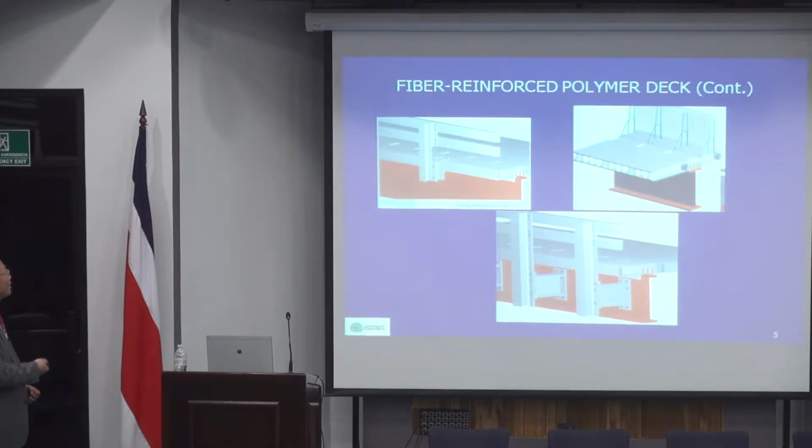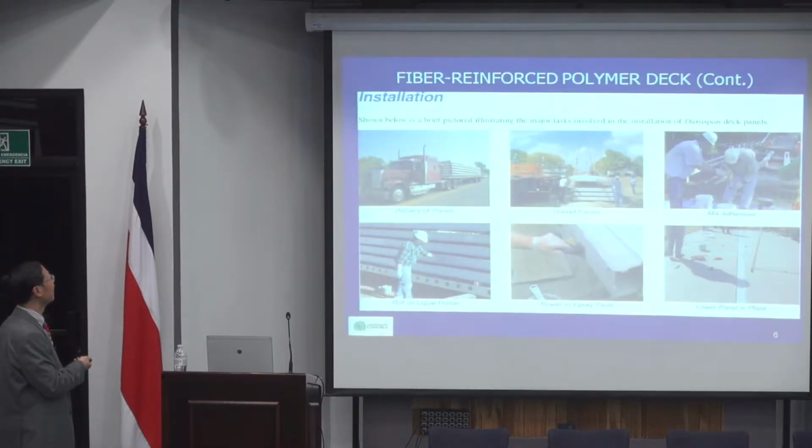And for the railing detail, they have a couple of these, but my recommendation is to design the railing independent of the deck, so don't put the railing on this deck, because we don't know what the performance may be. If you use these, that's okay, because that has nothing to do with the deck. Or if you use this concrete, it will be all solid concrete, so that will be something we know.